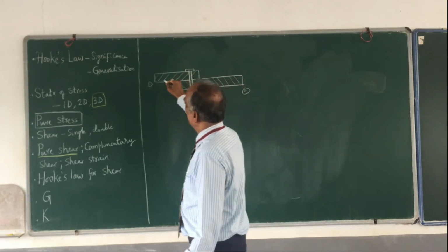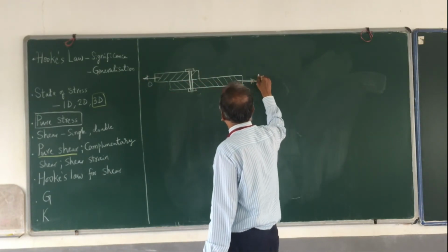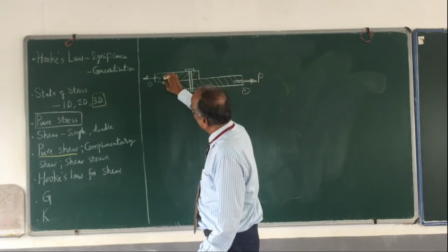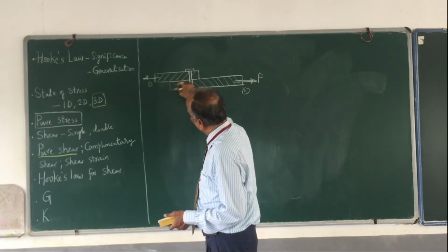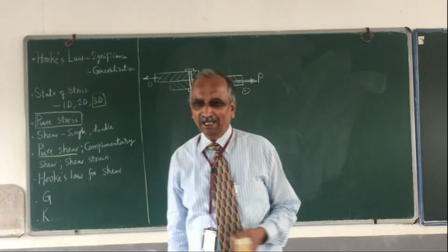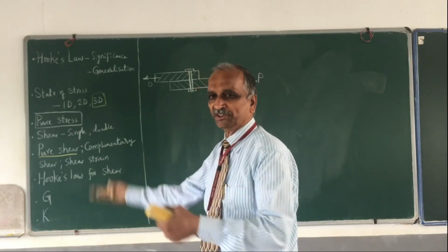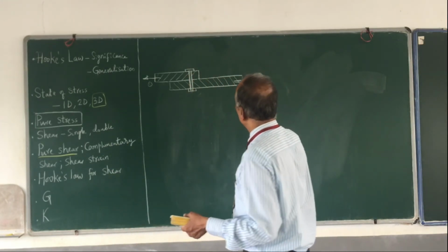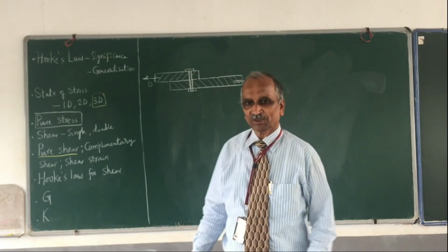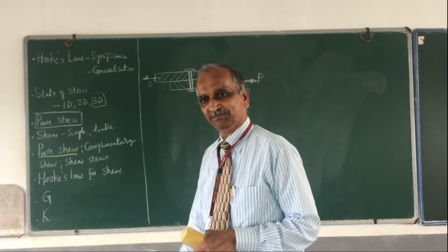Now what I do is I pull this plate this side and that plate the other side. The load is a tensile load. There is a small non-collinearity, a small gap here, but as the thickness is very small, I shall consider that effect some other time. Now you imagine that they are almost collinear. The effect of non-collinearity I shall take up separately.